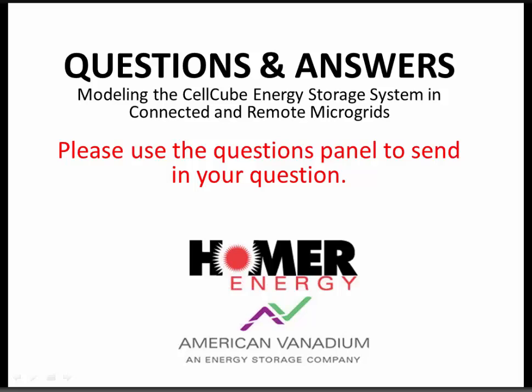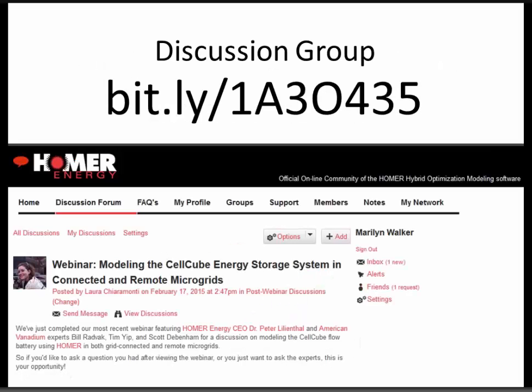In other words, you can be participating in, let's say, an ancillary services market where you're providing frequency regulation services. You can also supply voltage support services because we can provide kilovars. We can provide a black start capability. We can peak shift. We can make the solar peak coincident with the load peak. That may be a 4 or 6 hour difference. And we can do that all out of the same battery.